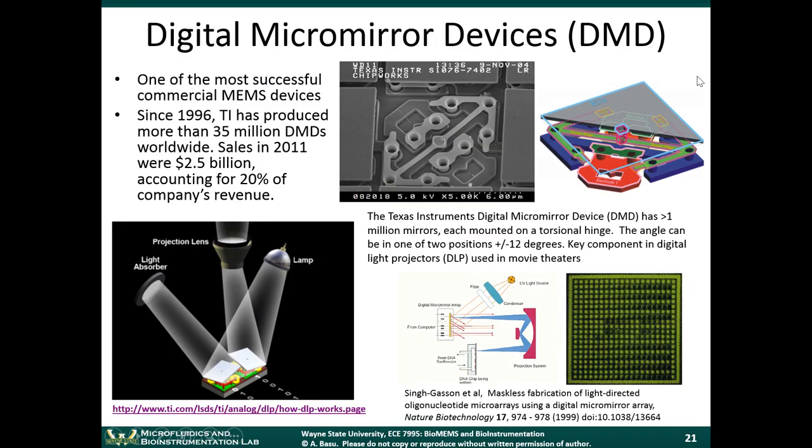All right, so the idea here is that these micromirrors can actually be switched from one state to the other, meaning at this angle or at this angle. The angle that they switch is about plus or minus 12 degrees. The way that they move is through electrostatic actuation. So on this side of the plate, they'll have a capacitor on one side, and a capacitor on the other side, essentially. Now, let me just draw this out. I think this will be easier to see.